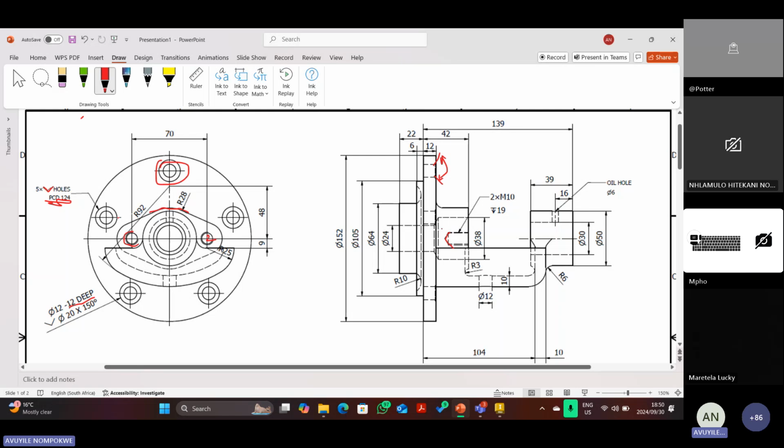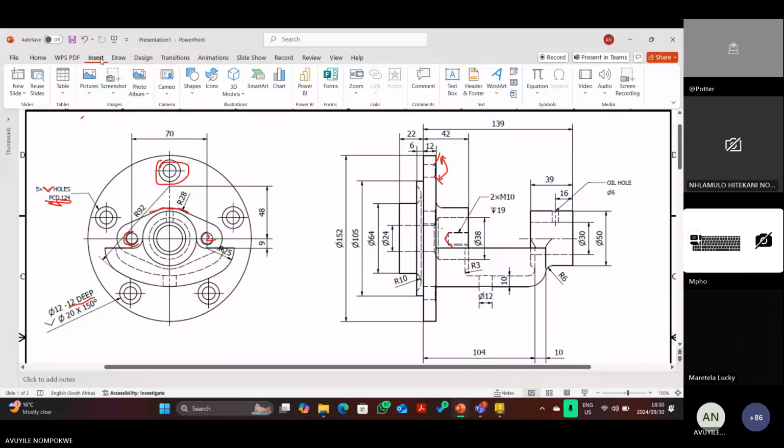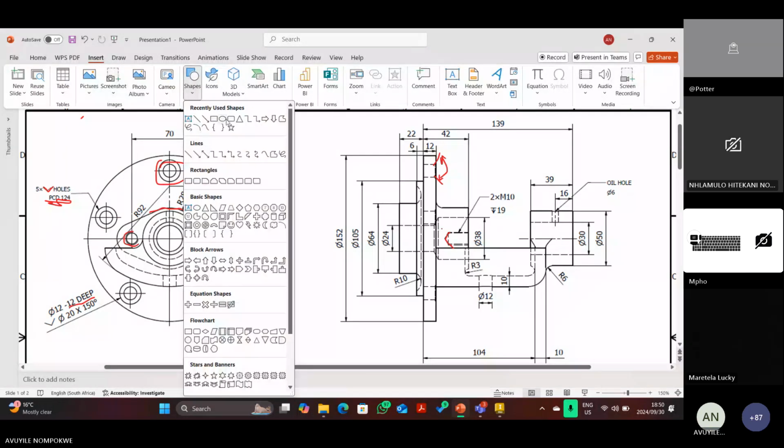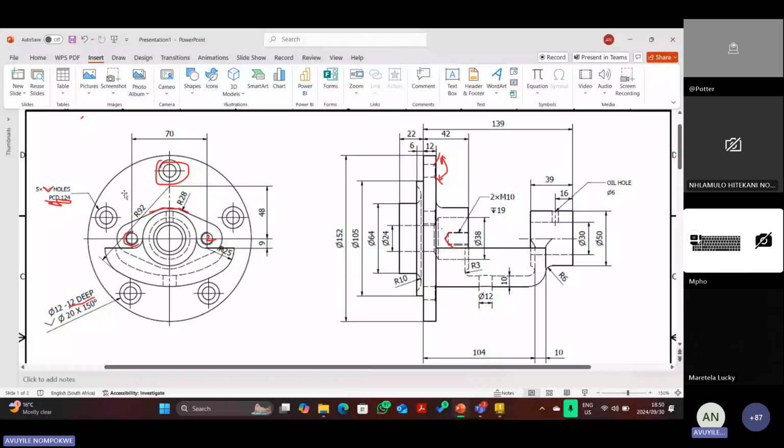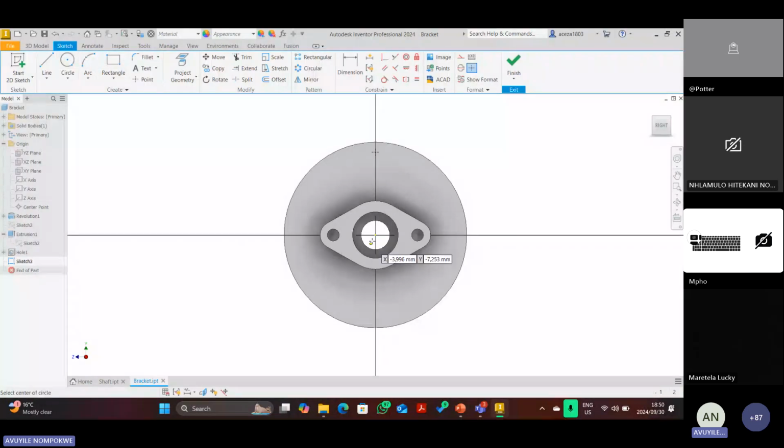And then I was saying, what is the distance from the center to that hole? We need this distance, right? So how do we figure out that distance? It's given that the pitch circle diameter is 124. Meaning that if you were to draw a circle that bisects these circles at the center, its diameter will be 124, so the center is 124 divided by 2.